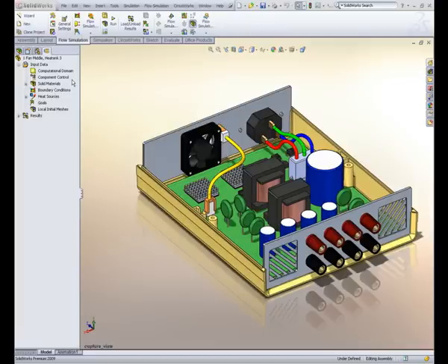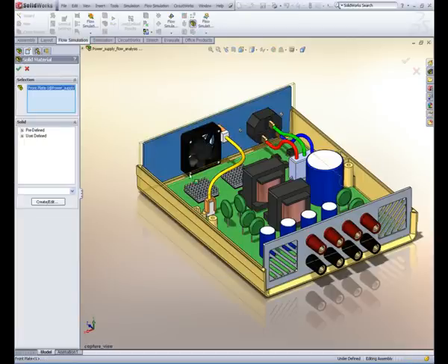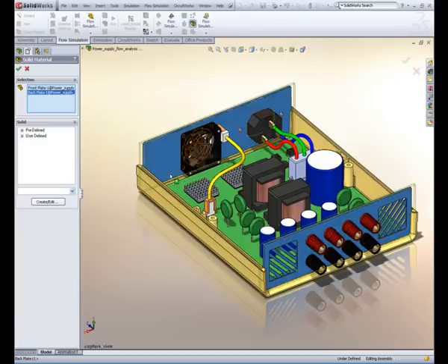For example, in our wizard we define the solid components to be made of insulating material, but this is merely a default. We can now define alternative materials to some components, leaving the remaining items the standard insulating material. So, by inserting a solid material, we can pick our end plates and define their properties as stainless steel.